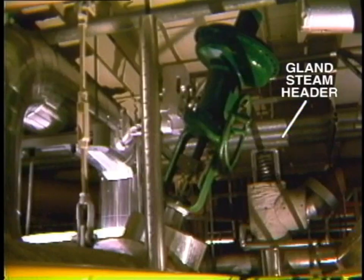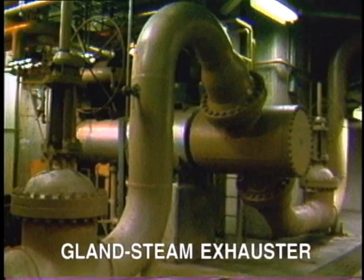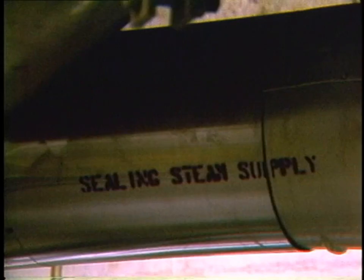Remember that there are two basic circuits in the gland steam seal system. First, the gland steam header, which supplies steam to the seals or dumps excess steam. The second circuit extracts leakage steam from the extremities of the glands and passes it through a heat exchanger and the gland steam exhauster. Make sure to check and learn details of your own gland steam system.